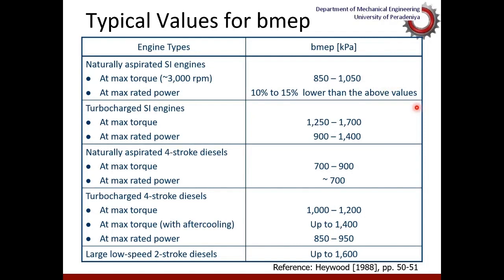But for the moment, as a simplified answer, the reason is the diesel engines are heavier and develop a lot of high pressure inside the combustion chamber during combustion and the expansion. Accordingly, the engines need to be made heavier and stronger.